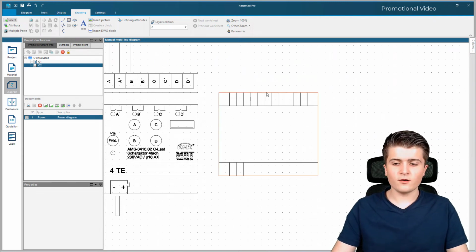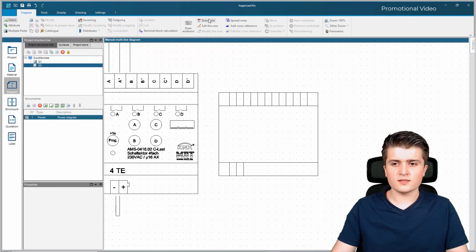So now, before I start to draw more, I first of all want to check if I can hook up the wires itself to the correct position here. So I start by drawing some wires here, and you can already see that this just fits fine. And now here, instead of the original symbol, also the connection is directly connected to the device and also always in the middle of those terminals.